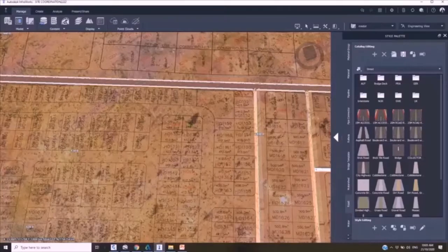Accordingly, we've defined for the other design that we've carried out, we define the range for what we need to see in the as-built model, which has all the detailed information that was needed in order to carry out our design criteria. So we have 25-meter road extensions or right-of-way, and this we have 20-meter road right-of-way, and we have 15-meter access street road. So in this case, I'm going to use 25-meter road right-of-way and the 15 access for the street road.